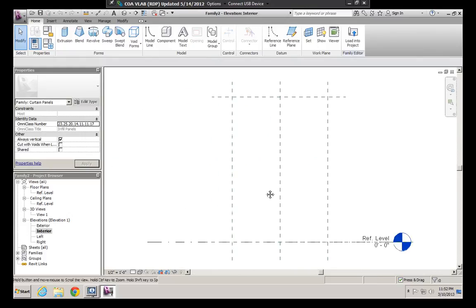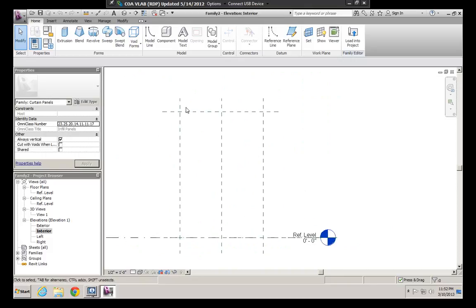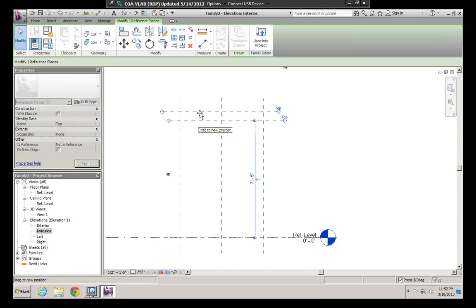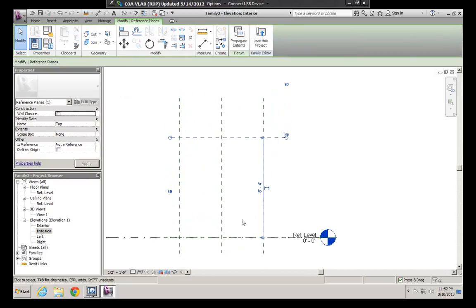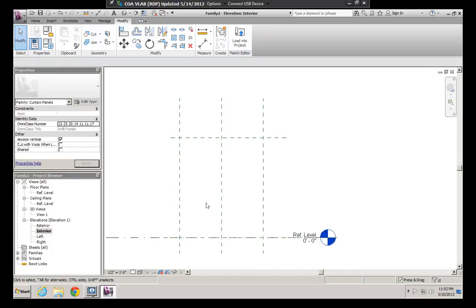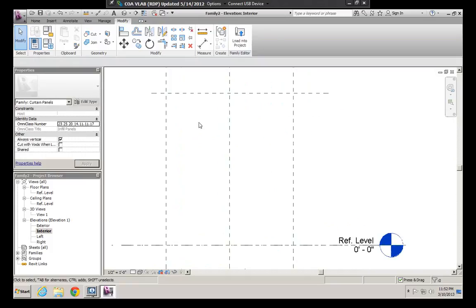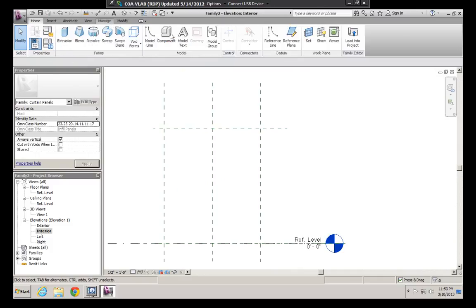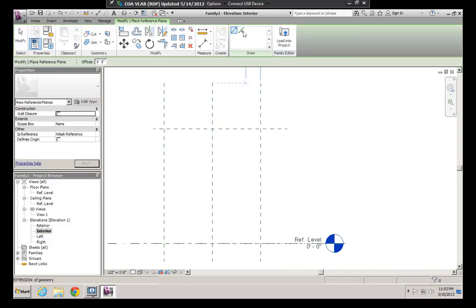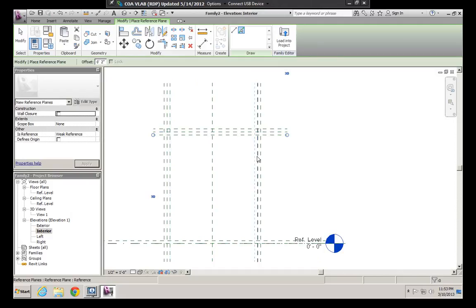I'm going to look at the interior view, and by default Revit gives us kind of a nice dimensioning template. So if you look at it, this will be the interior side, and these axis lines will define a tile. And what I'm going to do is just create some offsets here, and let's go to our Home tab, Reference Plane, and I'm going to pick lines, and I'm going to pick 2 inches, and I'm going to start offsetting some of these. And I need 2 sets of offsets.